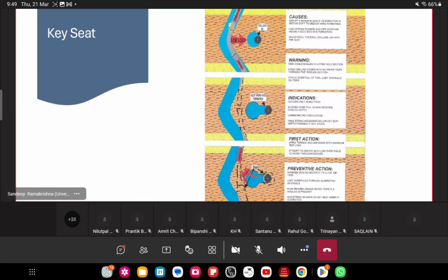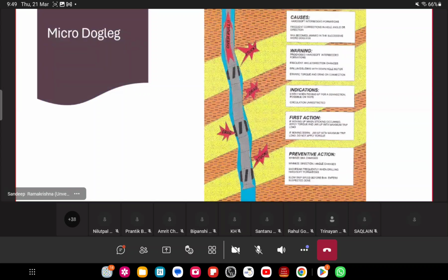you no longer have a good smooth wellbore, but rather you have something that is like a snake, right? And this constant change or the constant walk, one of the reasons is the sandwich nature of the formations through which you are drilling. So in this particular picture, that sandwich nature is depicted by sand, shale, sand, shale.